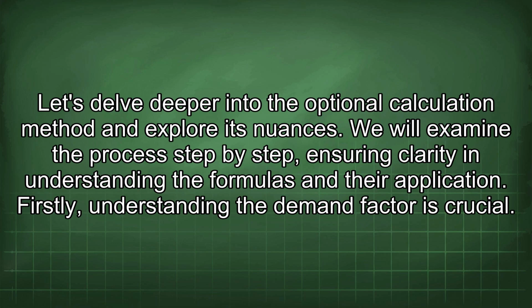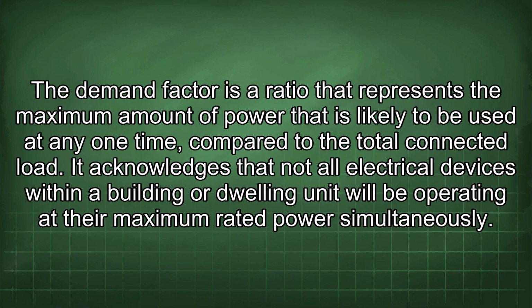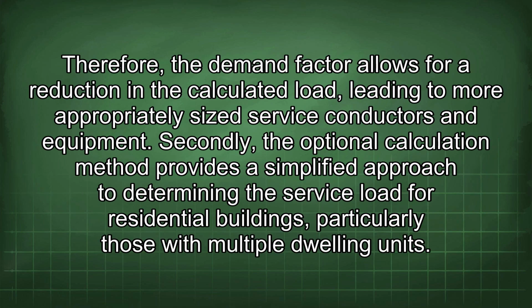Firstly, understanding the demand factor is crucial. The demand factor is a ratio that represents the maximum amount of power that is likely to be used at any one time compared to the total connected load. It acknowledges that not all electrical devices within a building or dwelling unit will be operating at their maximum rated power simultaneously. Therefore, the demand factor allows for a reduction in the calculated load, leading to more appropriately sized service conductors and equipment.